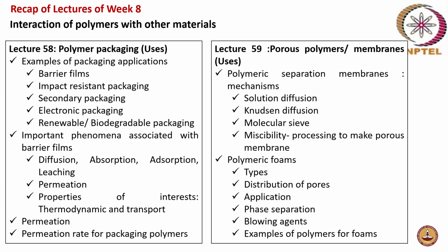And how do you actually bring in, either by a single processing, or you can create sandwich structures as well. And phase separation between your polymer and your gas phase. So what are the blowing agents used? The blowing agents can be of two types. It can be a physical blowing agent. That means a direct gas molecule like your carbon dioxide or nitrogen can be brought in along with your polymer, and then when they escape, the escape zone forms the pores.